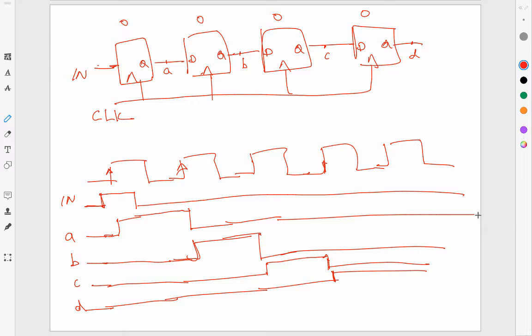The thing I wanted to point out was that while Mealy kind of sounds selective, in reality most of these signals are coming from other logic anyway, so they themselves are changing at clock ticks. So Mealy is used very, very rarely, usually only in very specialized circumstances. By and large, you should just stick to Moore design. It is safe. It's how good, robust design is done. And independent of that, there is nothing that you can do in Mealy that you cannot do in Moore, other than that little issue of the clock tick, clock delay.